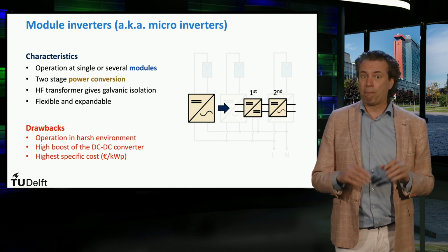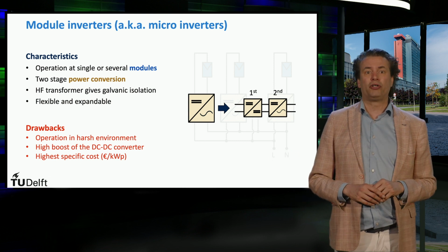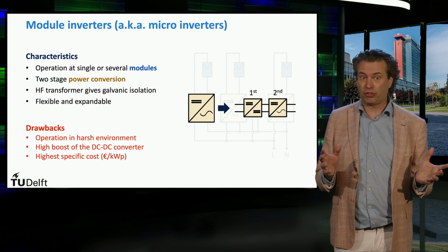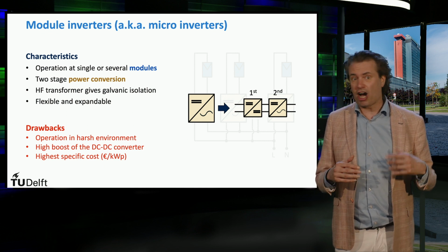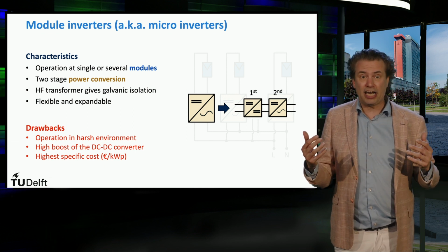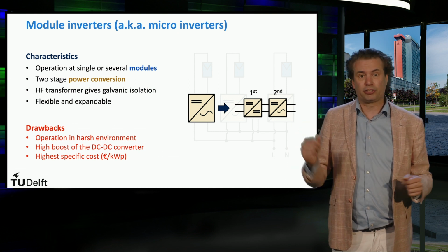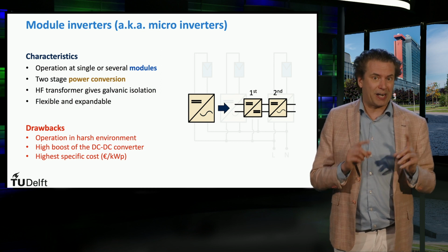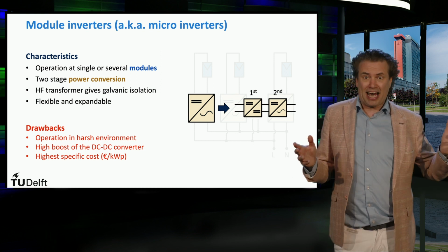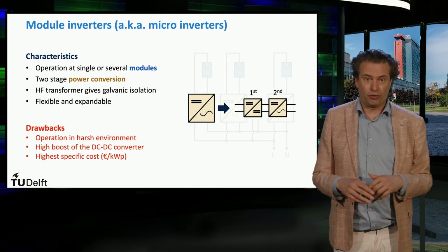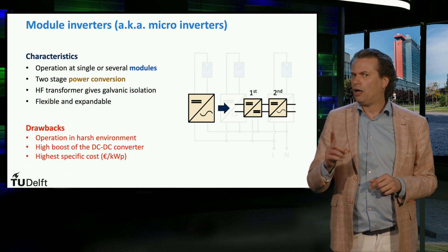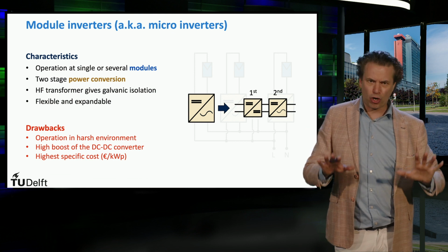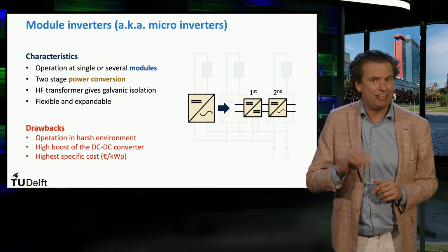Since these inverters are mounted on the backside of a PV module, their embodiment has to be very sturdy in order to operate in harsh conditions such as high temperature and large daily and seasonal temperature variations. Again, special attention should be put on safety issues related to cabling to avoid that animals bite the cables, resulting in conduction failures.